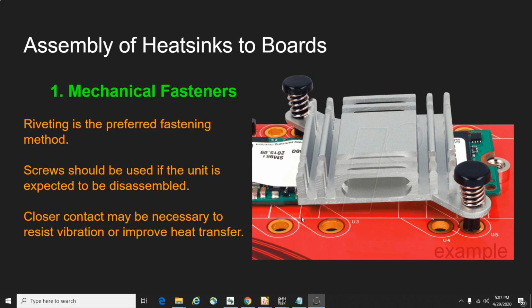And here the dry film epoxy adhesives are preferred over liquids, as the bond line thickness and squeeze out is easy to control. Bonding temperatures should be as low as possible to minimize the shape alteration in the PCB. Now moving on to the next slide.